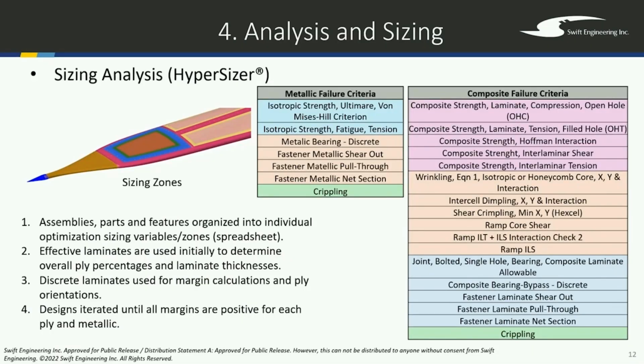Here's just a small image of the front part of the nose cone and some of the sizing zones we created. As you can see, the blue area is where they had a removable cover. They wanted to get access to their data recorders and some instrumentation they had placed in that little front area, so they wanted to be able to remove that. So that's a little cover at the front. The whole nose cone is basically made into two main pieces, because Swift didn't have an autoclave that was long enough, so we had to make it into 2 pieces.